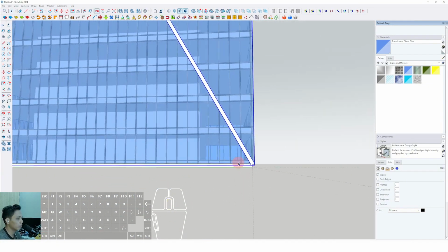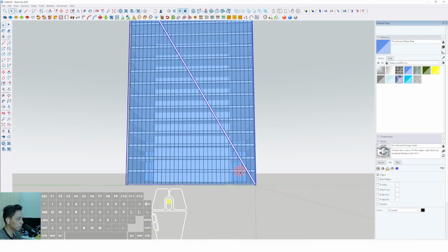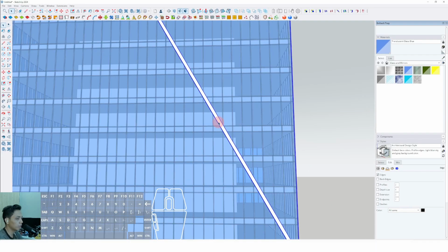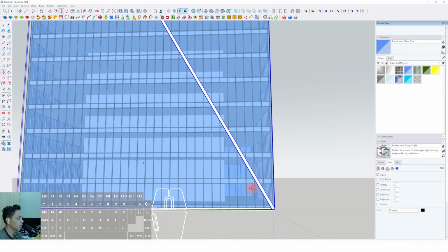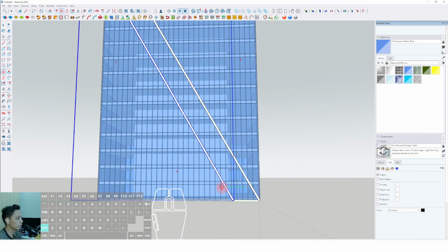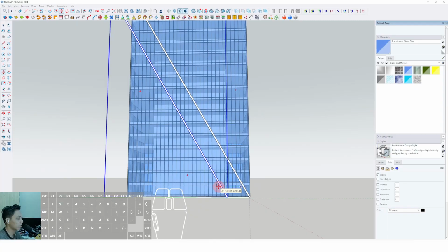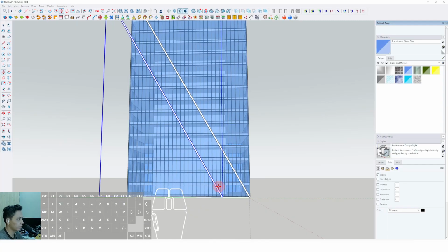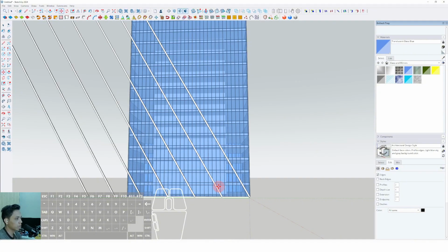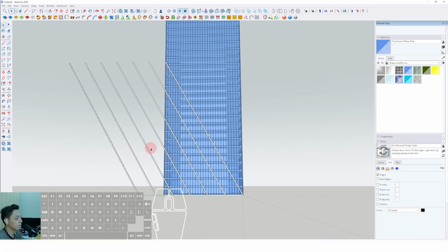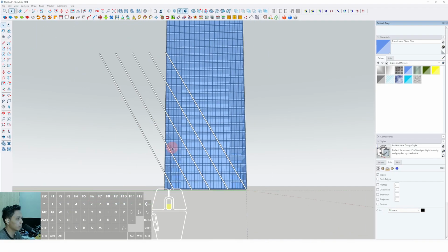Okay, and then we have to move and duplicate it. Select a move, duplicate to the another position around 10 meter, and then we can type x6, enter. Okay, we can delete this both of the frame.